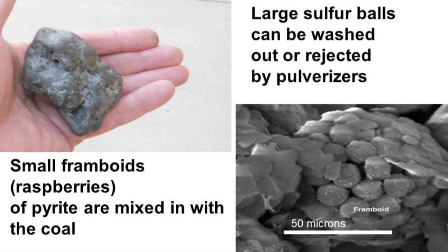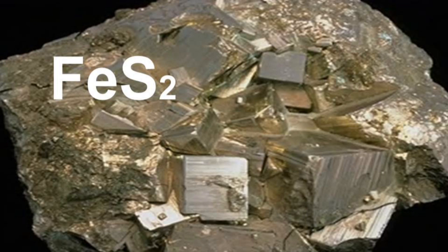But even on an opposed wall firing unit, usually they hit each other and spread out to the side wall. So there is this opportunity for large particles like pyrite and quartz, because those are the hard to grind material. And then keep in mind that pyrite is about 4 times the density of coal. In other words, the same size pyrite particle has 4 times the mass of the coal particle.